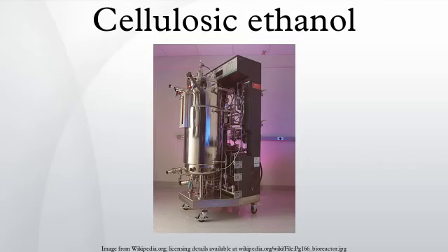Chemical pretreatment of the feedstock is required to prehydrolyze hemicellulose, so it can be more effectively converted into sugars. The dilute acid pretreatment is developed based on the early work on acid hydrolysis of wood at the USFS's Forest Products Laboratory. Recently, the Forest Products Laboratory together with the University of Wisconsin-Madison developed a sulfite pretreatment to overcome the recalcitrance of lignocellulose for robust enzymatic hydrolysis of wood cellulose.